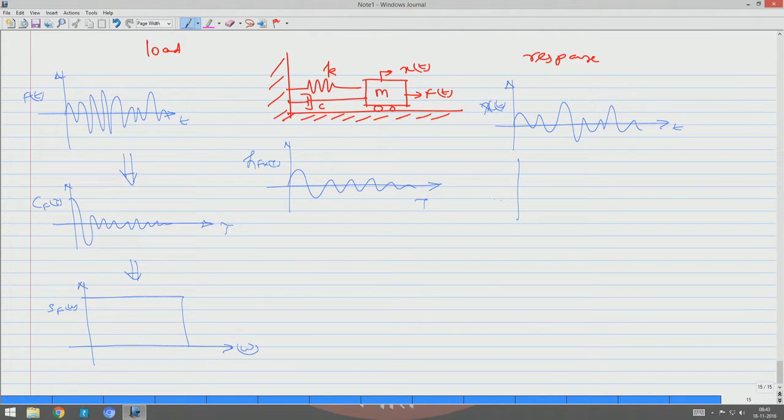Which can be seen in the traces of the autocorrelation function. So, when I try to apply the transfer function, I get a plot which is going to be similar to that of the dynamic amplification factor, but I am going to plot, let us say, h f x omega, which may typically look like this for any specific damping not equal to 0.